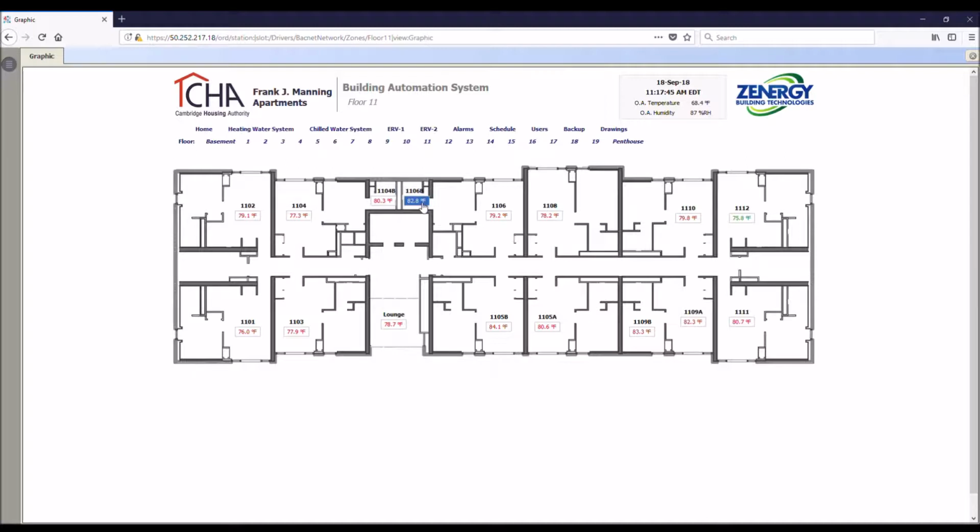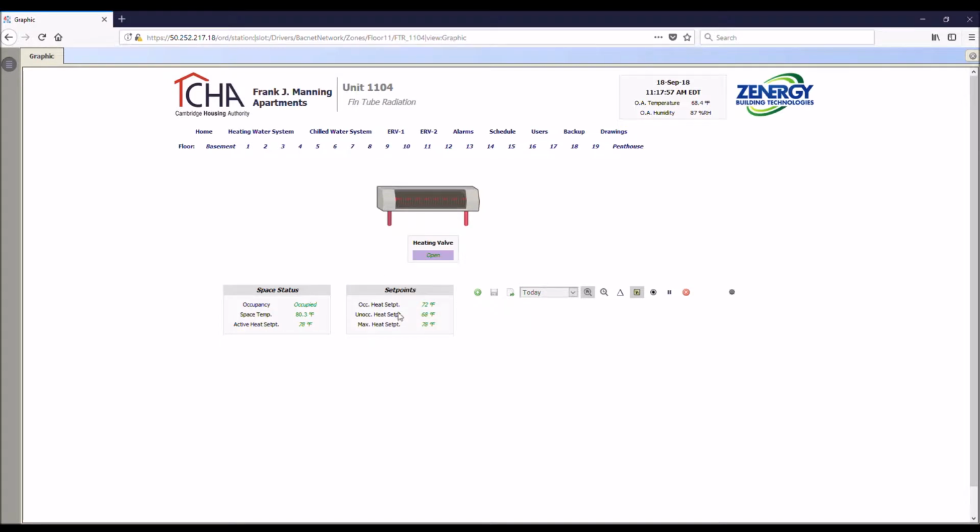On the bathrooms that are behind the elevators, we're using the same controller to control a baseboard radiant valve. So it's the same controller, but all it's controlling is the heating valve in that bathroom, either open or closed based on the heating set point, which we'll go over. Floors 3 through 19 are all pretty much identical.